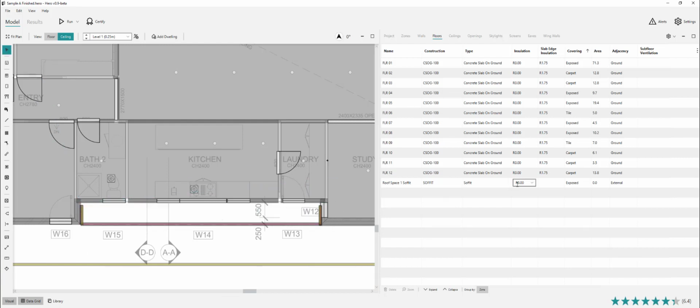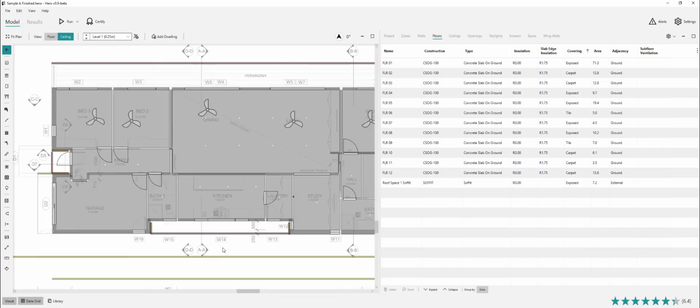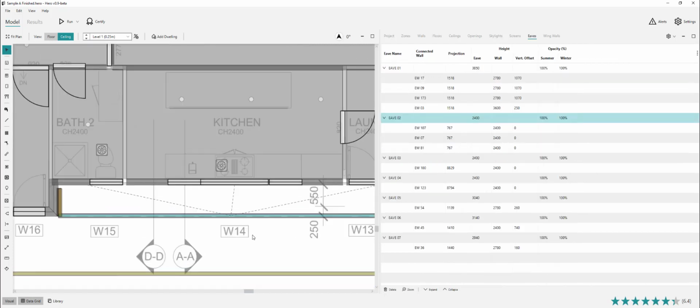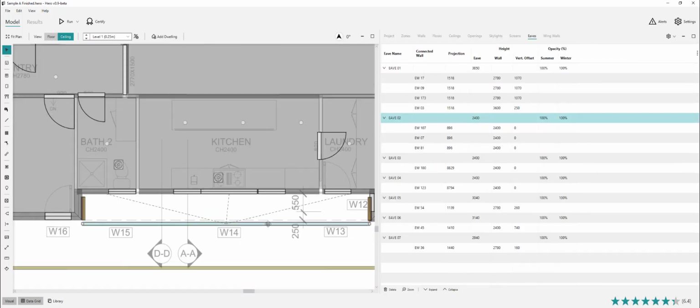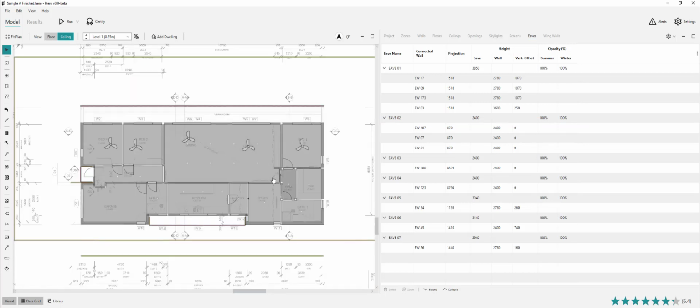7.2 square meters. So let's put in a 7.2 square meter uninsulated soffit into our roof space here. That's going to provide some additional accuracy to our model of what we might expect in reality. The other element I've realized here is that our eave here, under NatHERS TechNote conditions, should have that extra 100mm gutter dragged off it there.